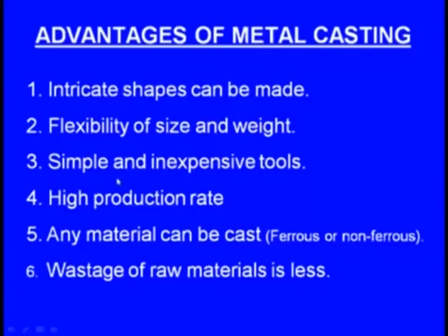Next one, simple and inexpensive tools. No high tech equipment is required for metal casting. The only thing is you have to create a hollow cavity in a compacted sand medium. For that, initially one has to use a model, which is known as the pattern. After creating a hollow cavity inside the compacted sand medium, we melt the metal and pour it into the cavity. So it is very simple and no costly tools are required. That is the advantage of metal casting.